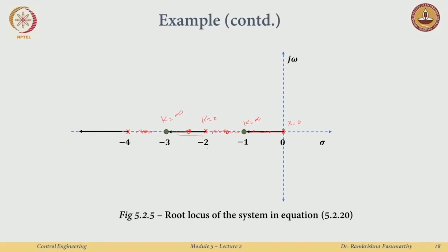Now, go here, to the left. Does this satisfy condition number 3? Okay, say 1, 2, 3, 4, 5 are the total number of poles and zeros. Of course, so this is on the root locus, and this entire real axis to the left is on the root locus, right. Okay. So, what does the second condition say? That when k equals 0, I start at the poles and end up at the zeros when k equals infinity. Similar things happen here.